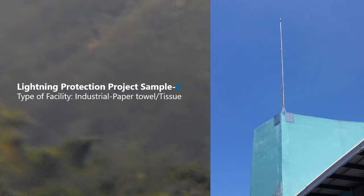Then for sample number 4, an industrial facility, a paper towel and tissue plant, installed on the edge of the concrete, at the top, at the edge. Mostly, as I said before, lightning protection system design is not prioritized in most facilities. They install it afterward. That's why lightning protection systems are mostly installed on the edge, because they don't have provisions for a down conductor.